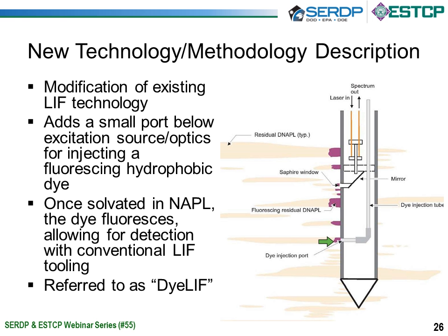And if there's any NAPL present or not, no matter what its composition, it'll fluoresce like crazy. So it could be corn oil, it could be any NAPL. It no longer has to have PAHs in it. So that was the idea.